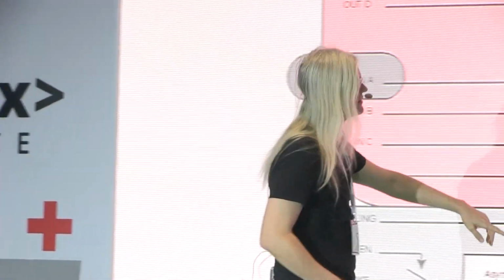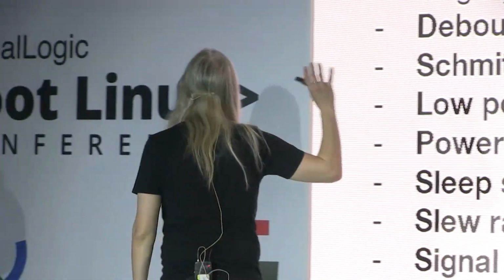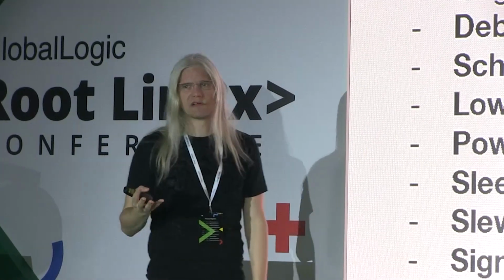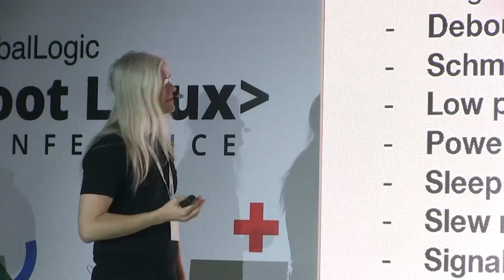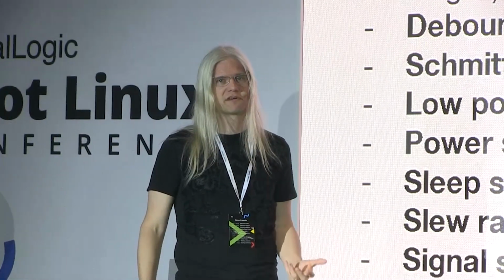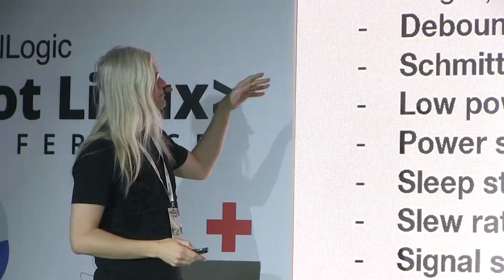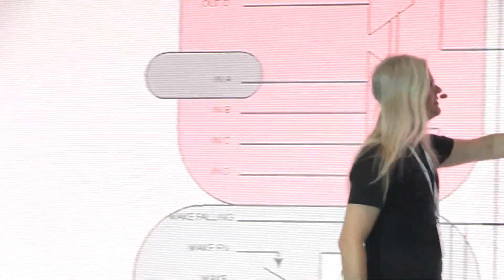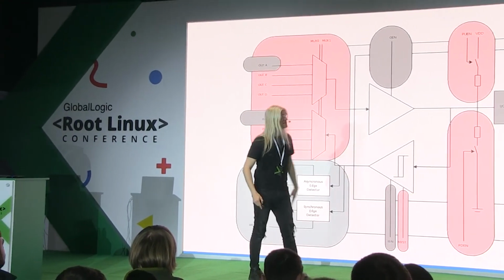Pin config, we're going to talk about the pink stuff, pin configuration. What is that? What kind of electrical control can we do from software? Yeah, we can do a whole bunch of stuff, and it depends on how much the silicon engineer exposed to us in software. Sometimes a bit, sometimes very little. Usually pull up, pull down. It's these 2 things here. We can pull up the line, pull down the line, which is necessary if you're doing open drain, for example, and also for other reasons.